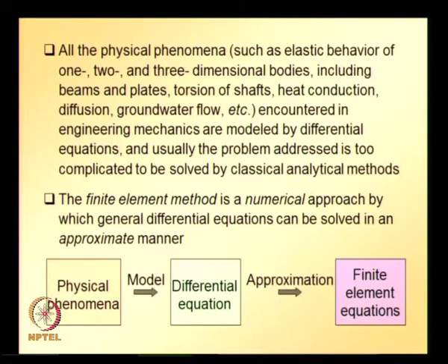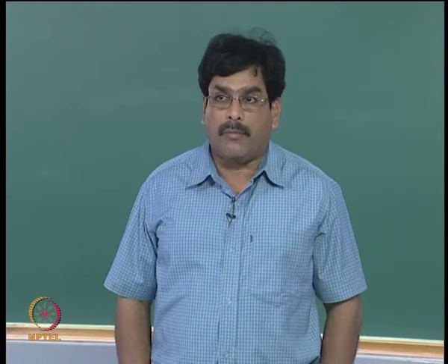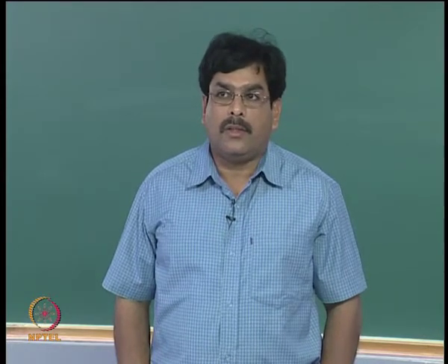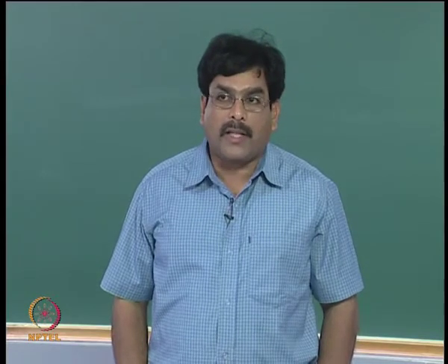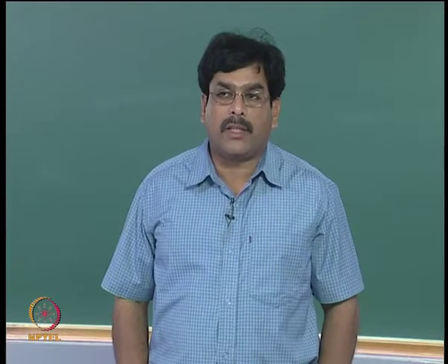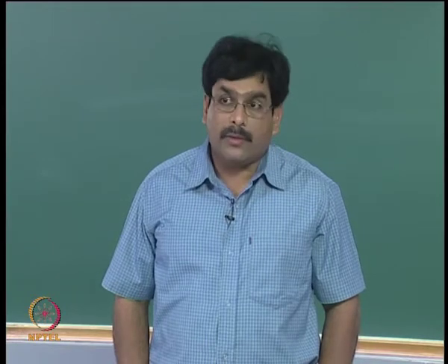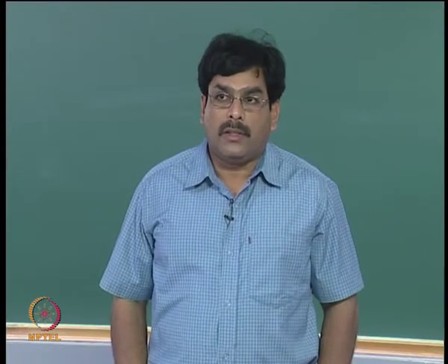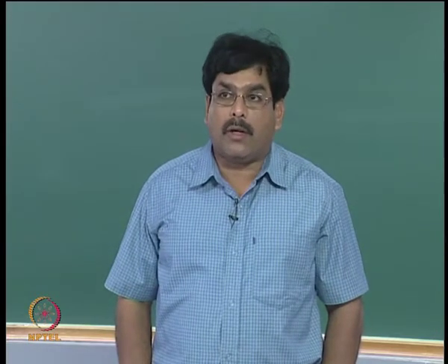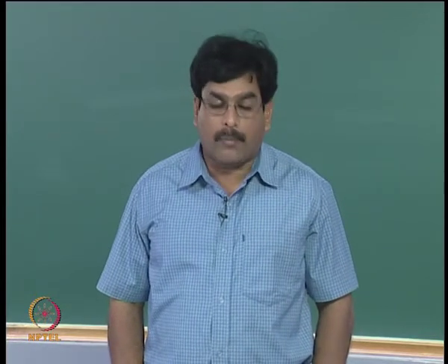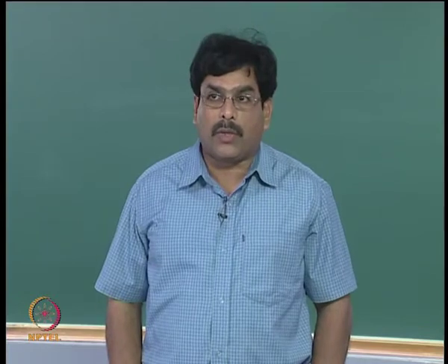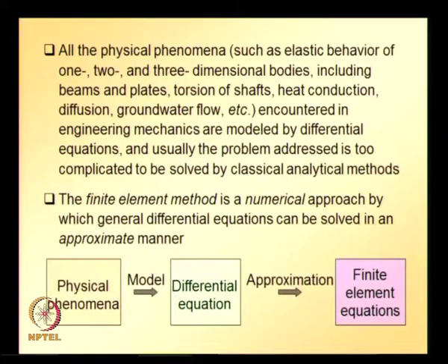So, basically finite element method involves discretization of the entire solution domain into some number of elements, and key points in these elements are called nodes. So, depending on the accuracy in the approximation that we are looking for, we can use elements having different number of nodes. So, the entire solution domain is divided into finite elements and solution is approximated at key points called nodes, and once we obtain the solution at the nodes, we can interpolate at any point in the solution domain using what are called interpolation functions or finite element shape functions. So, all those details we will be looking into in this course.